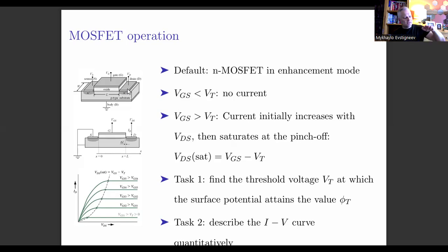The gate is an electrode, a metal plate, above the region between the source and the drain, just a metal plate. But it is not deposited on the semiconductor directly, because that would be stupid, because then this electrical connection between the source and the drain would always be on, right? So you do not want that.